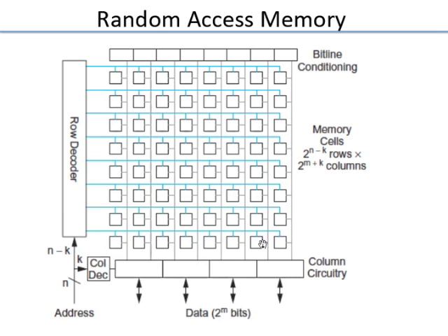Now from these 8 bit lines, here the memory has 4 bit output. So you have a 2:1 mux. You choose one of these pair of bit lines and get the data out. So you have an additional 1 bit to select which of the pair of bit lines you have to connect to the output. So you break up the decoding problem into 2 pieces. Row decoding to select the row and column decoding to select the column. And now you can access any 4 bit chunk here, any 4 bit word, in constant time, regardless of what the address is.